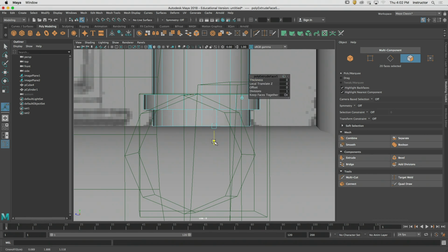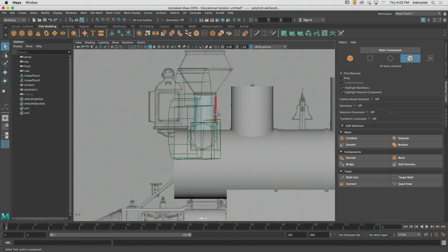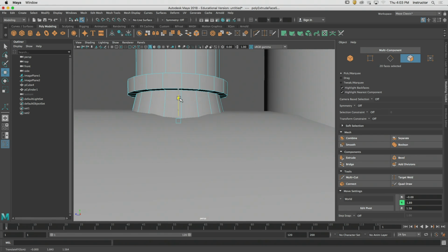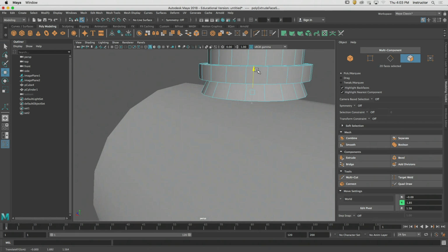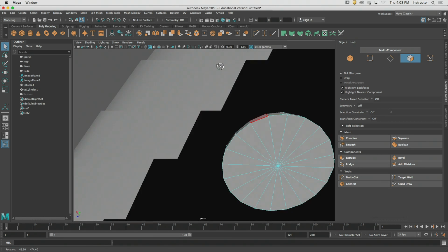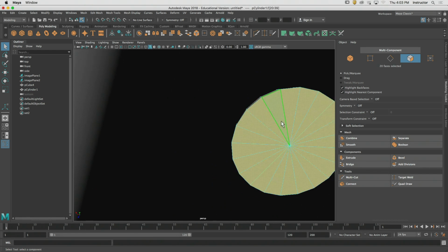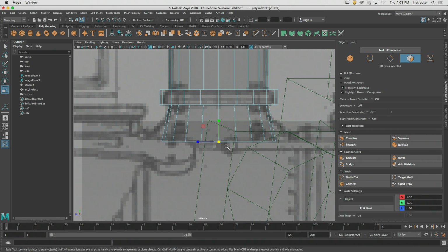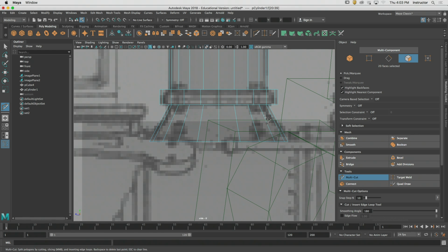One last extrusion. This one I'm also going to give a little bit of offset to create the taper. Okay. Voila! There we go. Looking pretty great. Now it needs to go into the bottom of that a little bit more. And it is totally okay to do that. You can completely bury polygons into each other. That is totally fine. It is absolutely allowed. It's part of our workflow, so don't feel discouraged to do it. I'm just looking at the size of that bottom polygon. There needs to be another edge loop in there to get the actual taper shape. Let's just do that real fast.